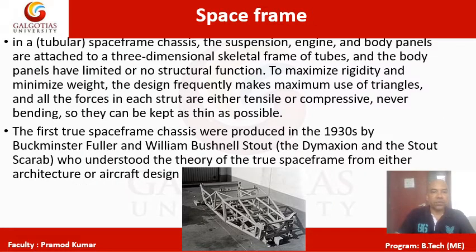The space frame. In the space frame chassis, suspension, engine, and body panels are attached to a three-dimensional skeletal frame of tubes, and the body panels have limited to no structural function, to maximize rigidity and minimize weight. The design frequently makes maximum use of triangles.